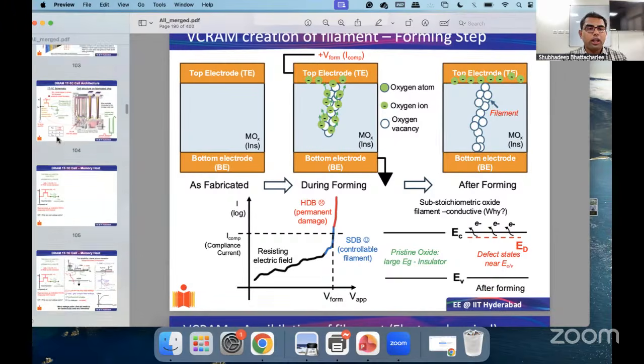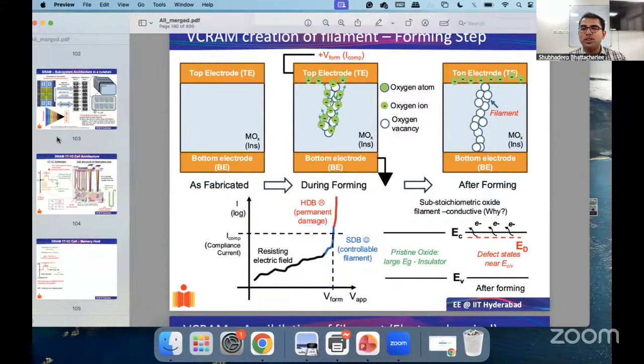Okay, so I think you are using terminology which is not universal. But first and foremost, you said that we calculate margins. The noise margins are not calculated for write. For write, noise margins don't make any sense. So we generally calculate hold noise margins and read noise margins, and at least for our course, we have restricted to the static noise margins only. Now, coming to your question, which corner cases are you mentioning?